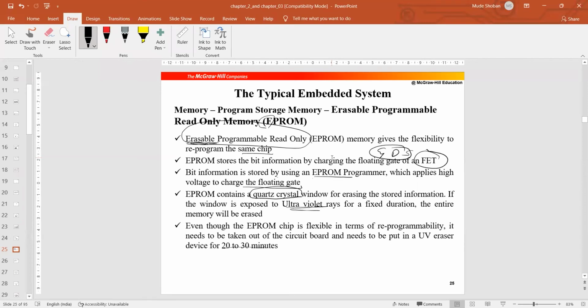Memory is not an easy topic that we are discussing, but the manufacturer knows what the content is, how many bits can be stored, and how compressed files can be stored. There are so many algorithms to compress the data, right? So here you could see the EPROM. To erase it, you can remove the memory chip and place it in the UV eraser.